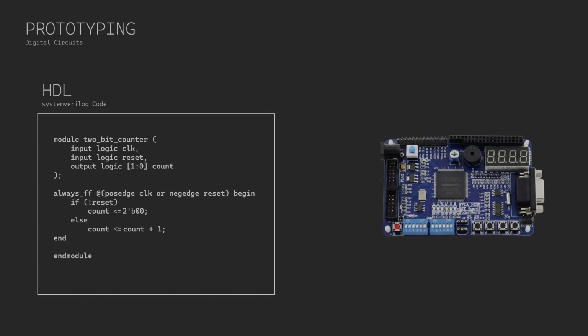In this design, the 2-bit counter circuit for the FPGA was created using D flip-flops, rather than the JK flip-flops used in the earlier breadboard-based design. This is because the flops available in the FPGA are D flops, although the underlying functionality remains the same, counting from 00 to 11 in binary, equivalent to decimal values 0 to 3. Let's power on the FPGA board. You see nothing happens, because the FPGA is not programmed and now it is like an empty breadboard.